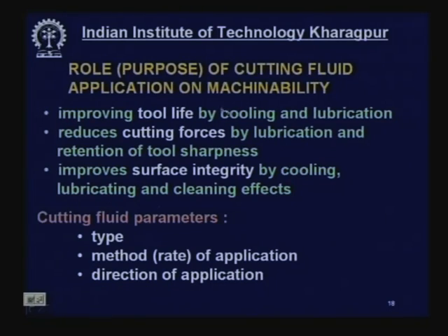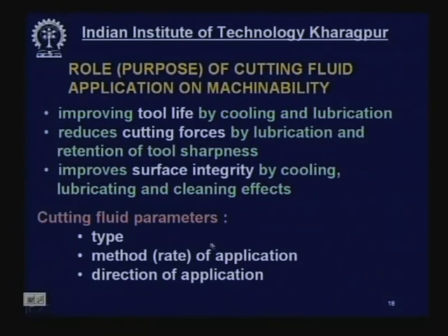So, these are the beneficial effects of cutting fluid application in respect of tool life, cutting force and surface integrity, all of which are nothing but the criteria of judgment of machinability. So, machinability is substantially improved by this process if judiciously selected. The cutting fluid parameters are also to be taken into consideration. What type of cutting fluid you are going to use will depend upon the tool material, work material and type of rough machining or finish machining. How do we apply, drop by drop or by flood or by jet, the direction of application from top, from back, from front, all these things will matter. This will decide the effectiveness of cutting fluid application.